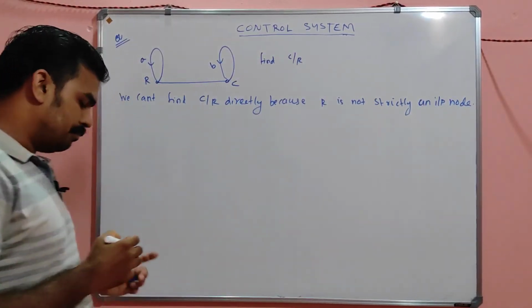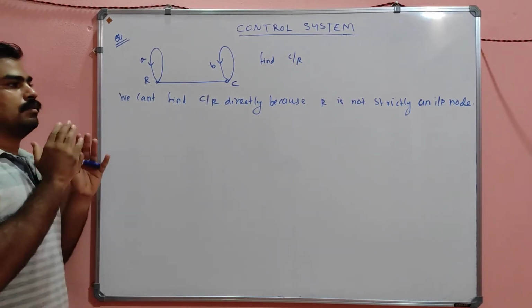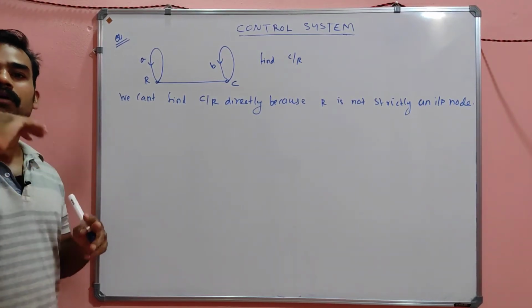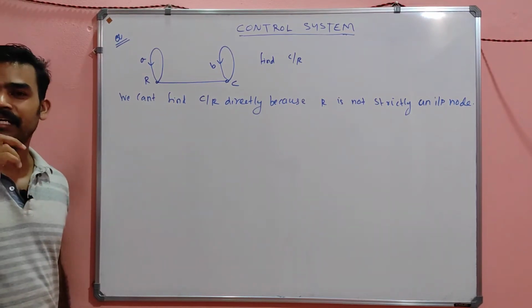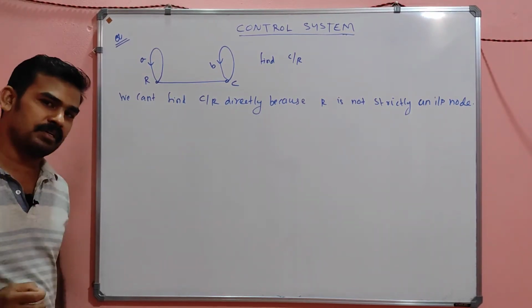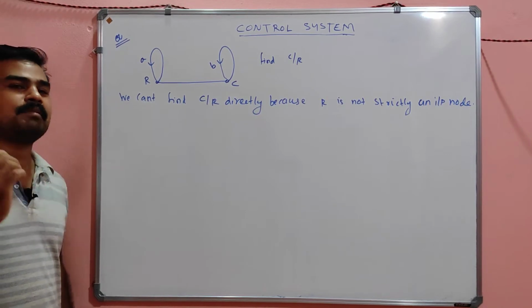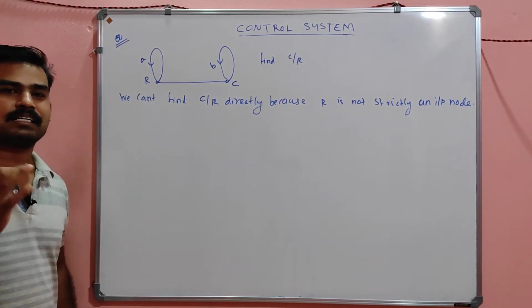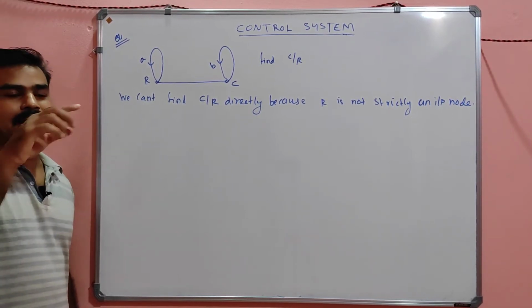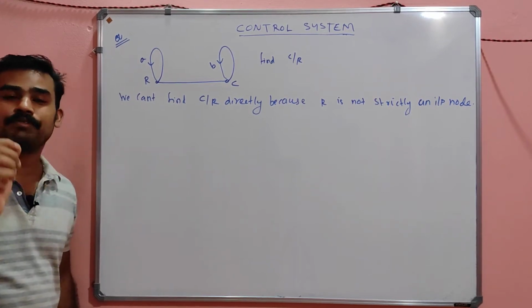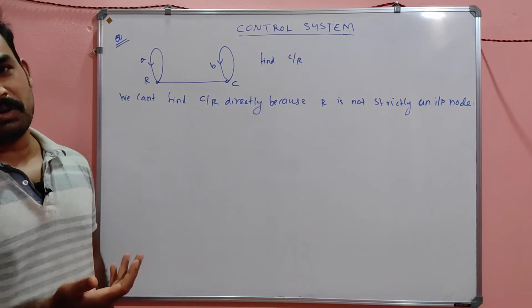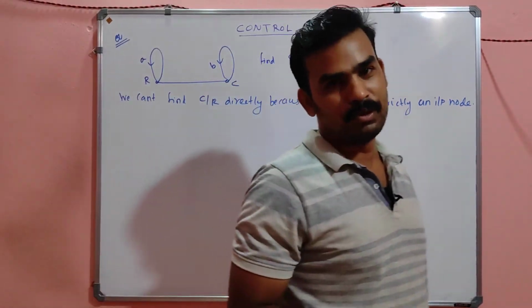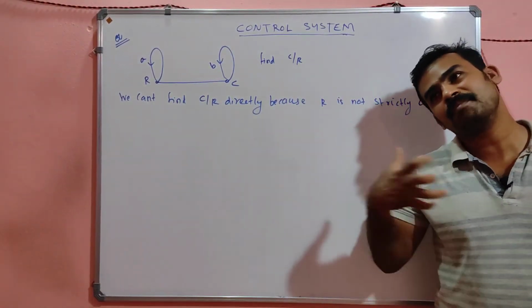I already mentioned that for an input node there are only outgoing branches; then only it can be considered as an input node. If there is any incoming branch there, we can't consider it as the input node. In brackets I mentioned strictly follows. In the case of an output node, it need not strictly contain all incoming branches.